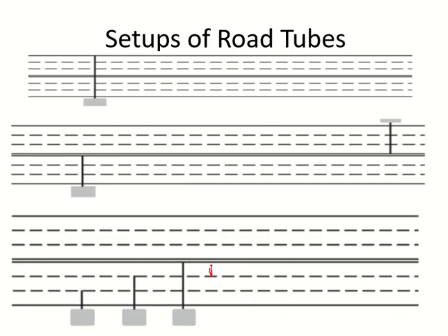So I'll put the tube over here and I put the sensor over here. This can be done as well, and it will also give you the count for one lane, the outside lane. But they are doing it like this, no problem. The middle lane is problematic, because your tube will go from the lane all the way to the end for the sensor. The sensor has to be on the side of the road.